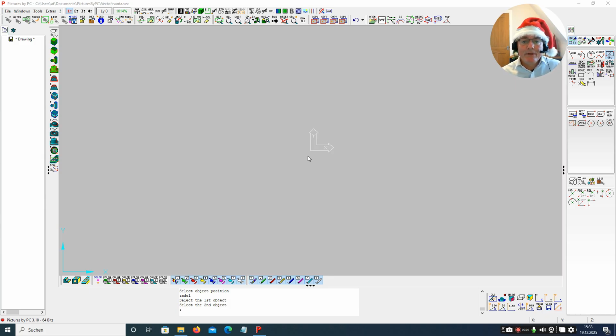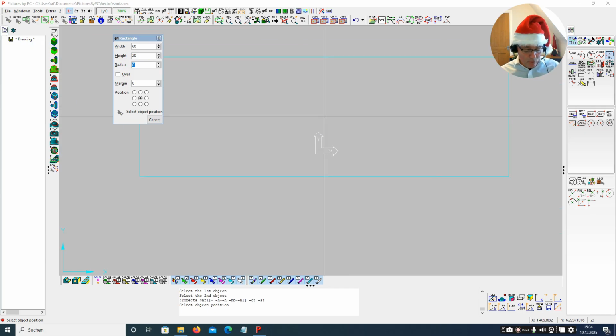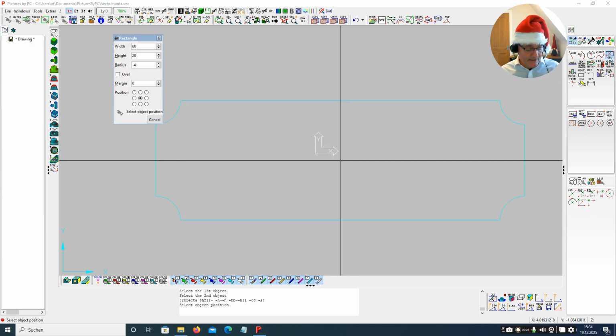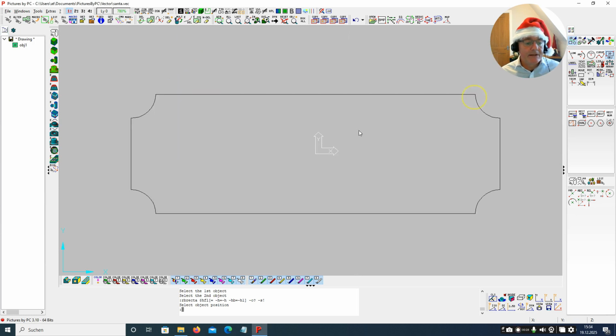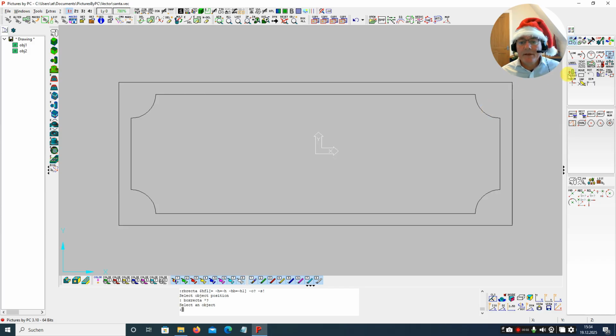Here we're going to be looking at the subject of industrial engraving and carving, so embossed features, stamps, dies, nameplates, even jewelry, woodworking. So to do that, we're going to create a nameplate. So 60 by 20 is good. It looks a little bit boring, to be honest. So let's create a negative radius in the corner. And we're just going to create an offset around the outside of 2 millimeters.